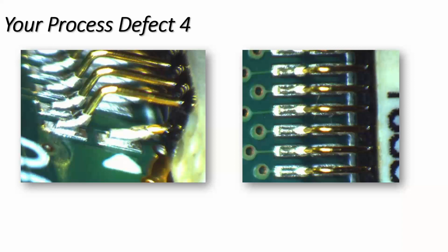Another thing that you should do that the customer has already tried is modifying stencil apertures, putting a larger volume of paste. And certainly that's the first thing I would have done in this situation. I would have looked at increasing the paste onto the solder mask, bringing it perhaps as far as the end of the track just prior to going into the via holes.